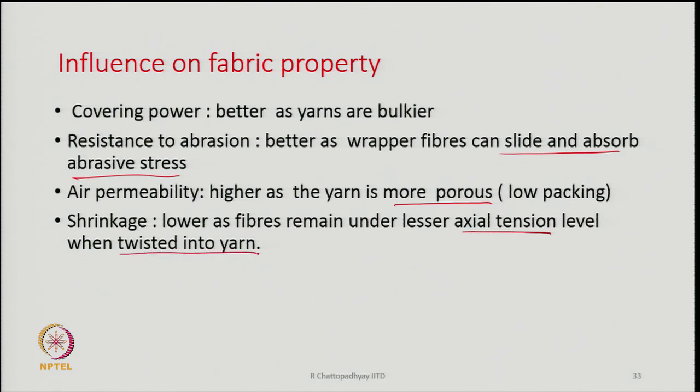If we take the yarn and dip it into water, we will know that the yarn shrinks. Now, this shrinkage depends upon the spinning tension under which the yarn was spun. In the ring yarn, the spinning tensions are always higher. There is a big balloon, there is a traveller, and the entire balloon and traveller have to rotate, and there is friction on the ring and traveller. So, as a result, the spinning tensions are very high.